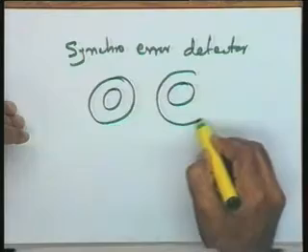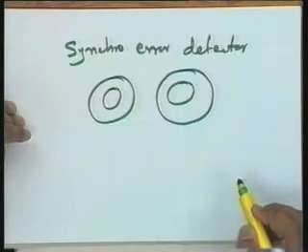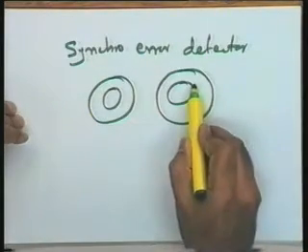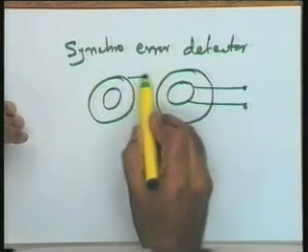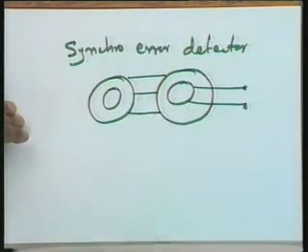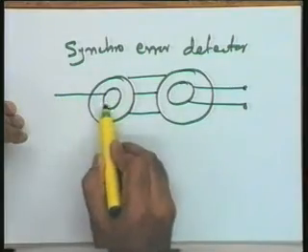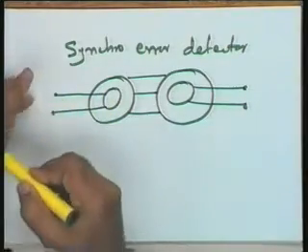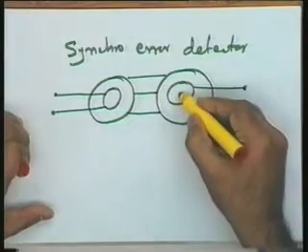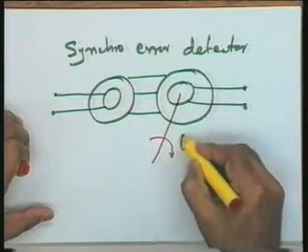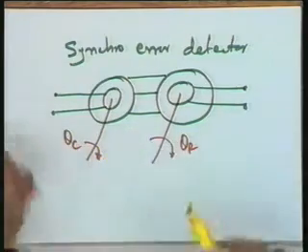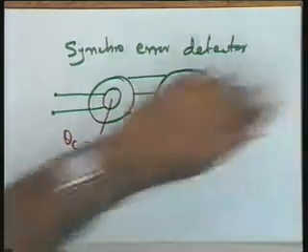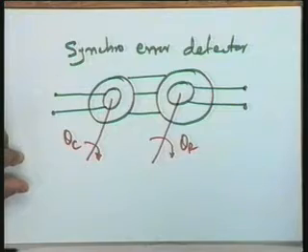There is no need of showing all the windings, rotors, etc. all the time. Let me say that this is the rotor of the transmitter, the 3 stator connections here, and this is the output of the control transformer, and here I have theta r and here I show theta c. This becomes the symbolic representation, a symbol showing a synchro pair. I will be mostly using this when I take up feedback control systems.